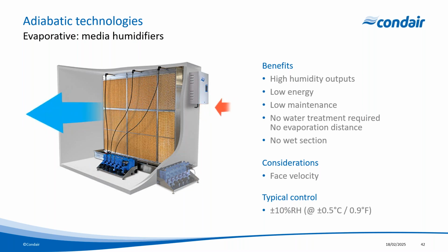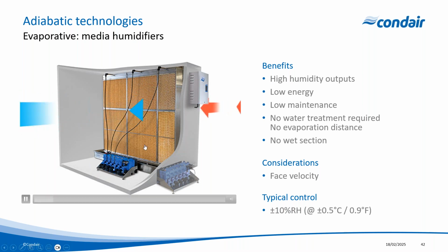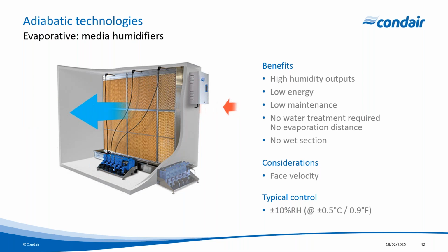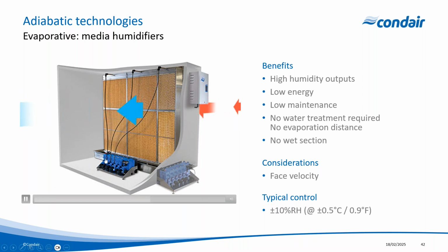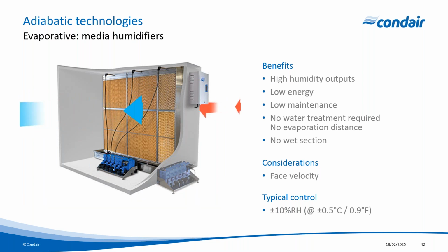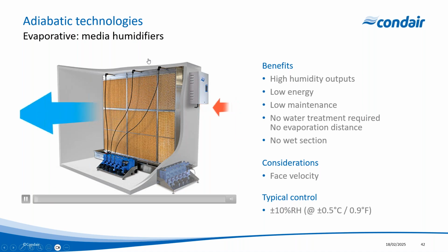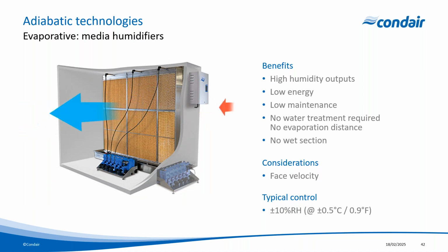So how it works is it's typically sized to match the internal dimensions of the air handling unit or the duct or the plenum, and we can actually have multiple units installed like we saw with the Meta case study. Air is pushed through an evaporative medium. In this case, it's a glass fiber matrix. Now there are other materials available for that matrix within these types of systems, but generally glass fiber is the most common for data center applications simply due to the flame or fire and smoke ratings.